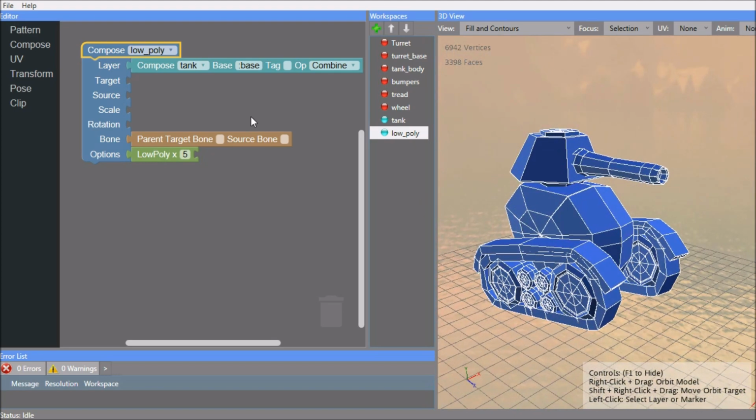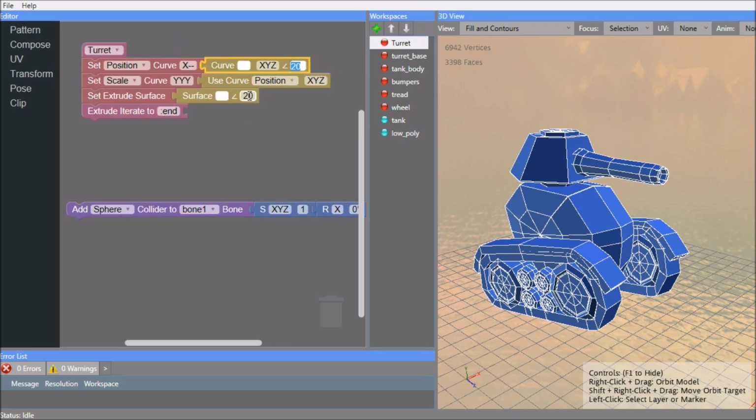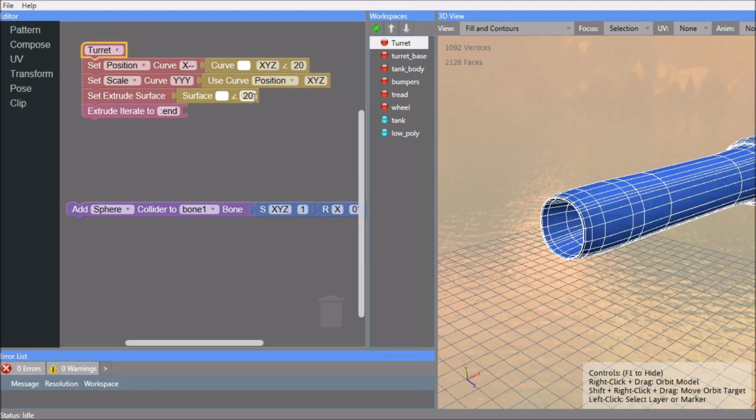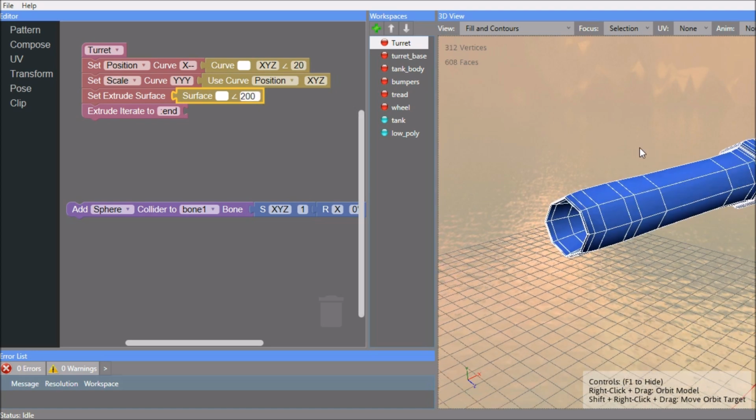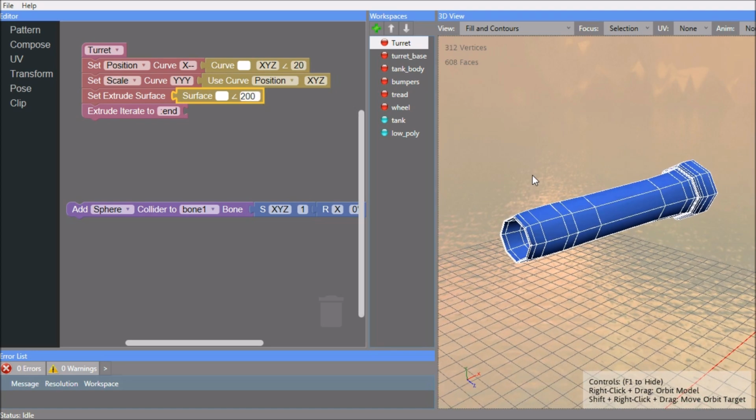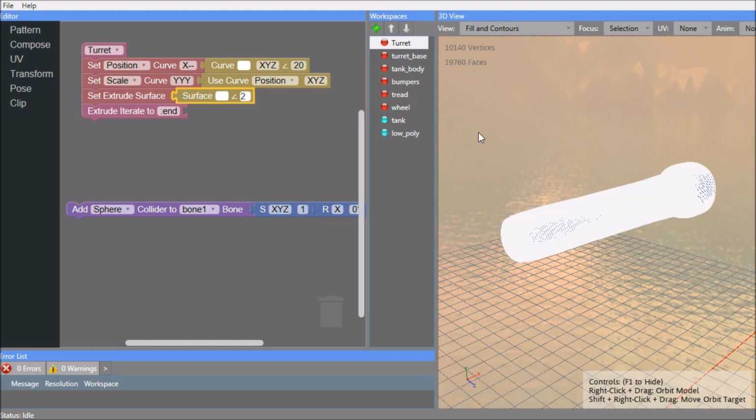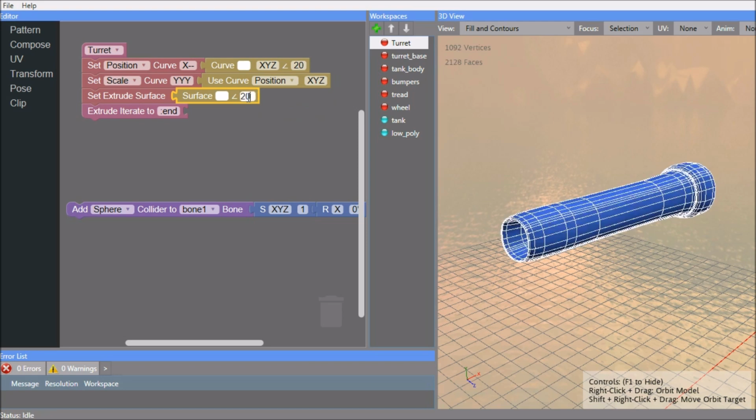This number here, 5, is applied to these numbers here on each pattern, and these numbers specify the degree of change when converting a curve into line segments. A higher degree of change will result in fewer line segments, meaning fewer vertices, and a lower degree of change will do the opposite, adding more vertices. So the low poly style is achieved by having a higher degree of change.